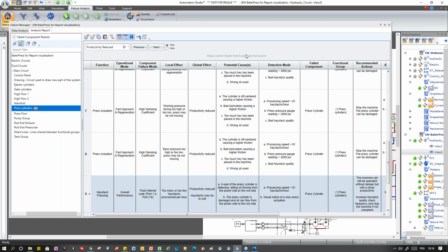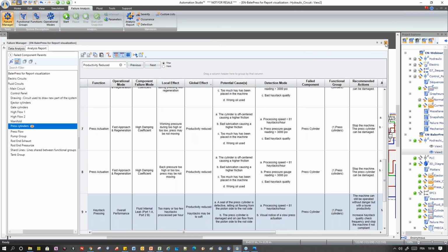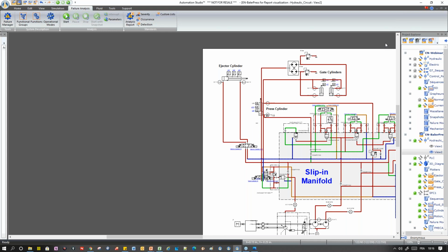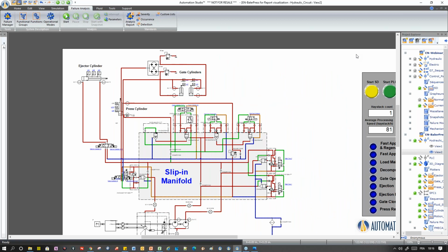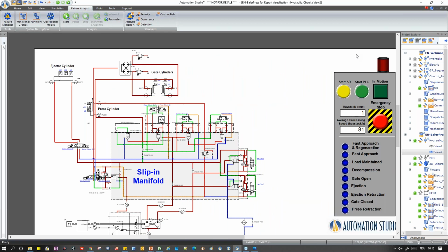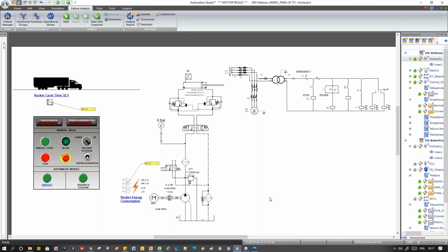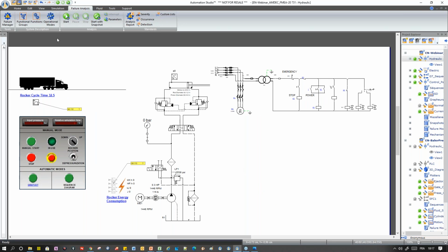But there is another usage in the report when you want to simulate specific things. For example, if you have a machine with different options and you want to simulate the machine with no option, you can declare a functional group for each option, and you will be able to simulate all the options using the functional groups. I don't know if it is the objective, but if you want, I can show you quickly in my system here how to create a functional group.